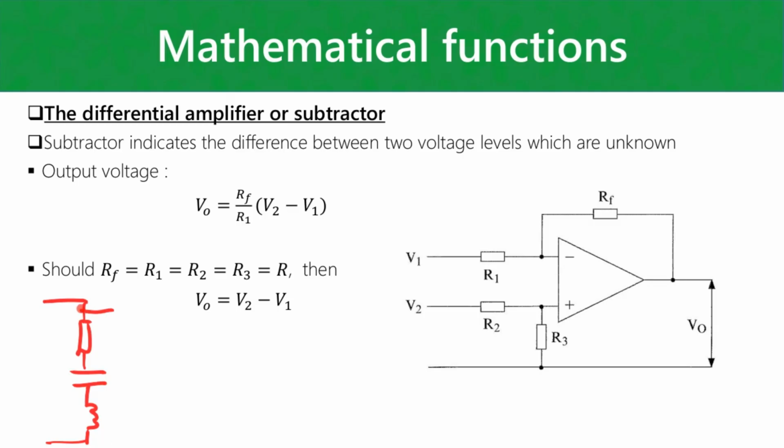You cannot measure like this, because one terminal of your oscilloscope probe is grounded, so you're basically shorting out the other two components from the circuit. This is where this op amp comes in handy. Now you can connect the op amp across the resistor. You're basically measuring the voltage drop across the resistance, or the difference in voltage levels.